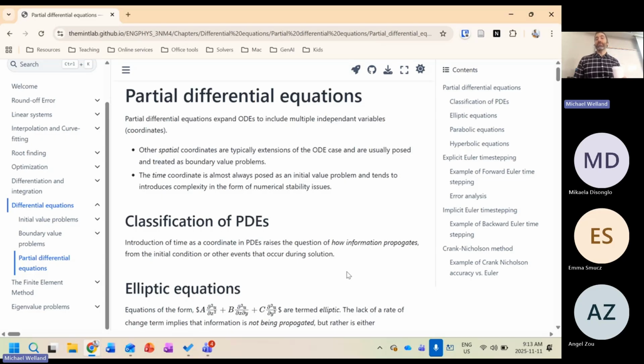What we're going to find, though, is that a lot of our analysis for implicit versus explicit time steppers is going to carry over almost directly. So a lot of the time with CFD codes, first of all, CFD is going to really favor finite volume because it has that implicit conservation built into it. But it's also just going to do explicit time stepping. All that means is that you need to take really short time steps, but you're still kind of robust.